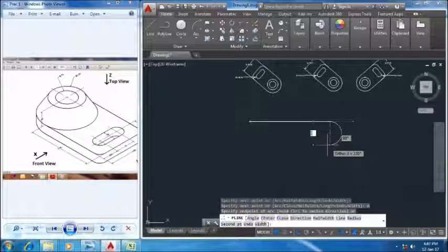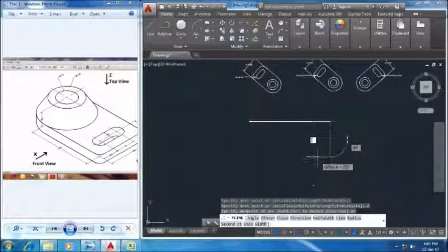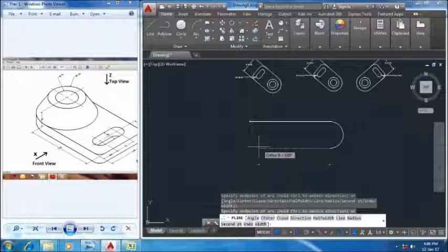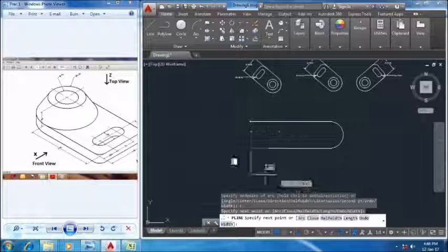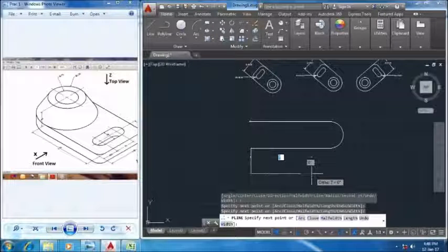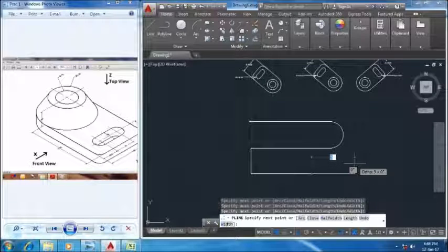You can see here we can draw an arc. Again, if you want to draw a straight line, just go to the command bar at the bottom and select the line, and hence polyline helps us to easily draw any object with the arc or the line continuously or simultaneously.